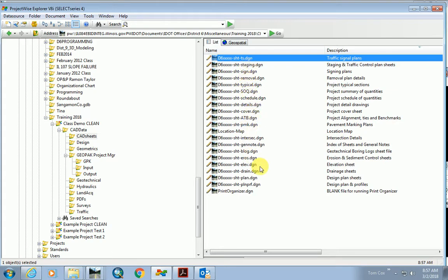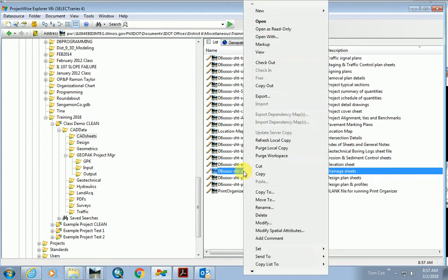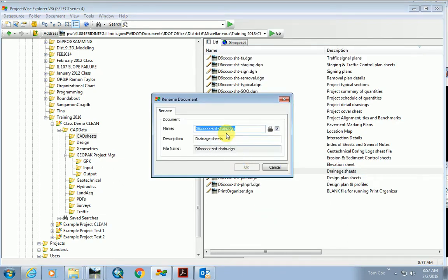Typical section. Huh. I'm going to have to go back to our main template and add that in. I don't know why that's missing. Well, let's just take one that's out there right now, and we'll just rename it to cross-section, XSEC. Maybe main line. We'll say OK.